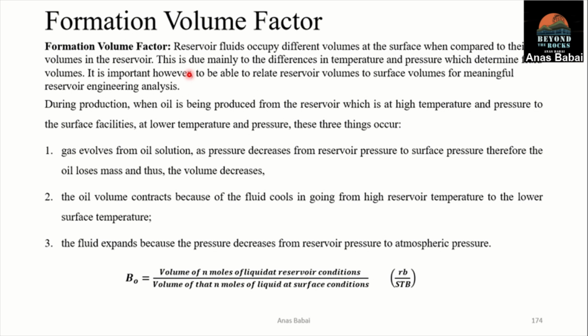some of those changes: gases which are involved in the oil solution under high pressure, when we decrease the pressure by taking this hydrocarbon to the surface, those gases will be released, so we lose some of the mass of the solution, and thus the volume will also decrease, because if those gases are in liquid phase under high pressure, when we release this pressure, those gases will be transformed from liquid into gas and released, so the volume will decrease.